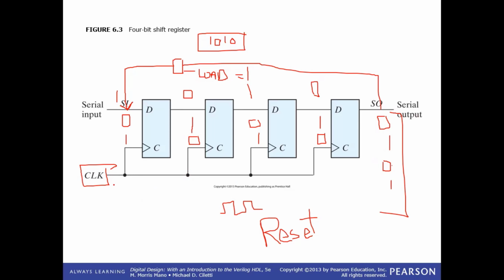If I had placed an AND gate at the clock, I would say that I am retaining the output by just putting the clock off. Is that right? Is everybody attentive to this? Yes, sir. I could have retained the output by pausing the clock for this shift register, but I didn't do that. I would never do that until and unless it's just inevitable.